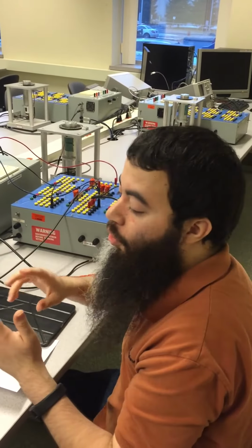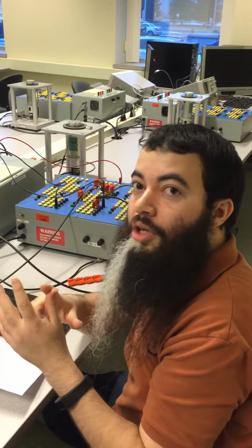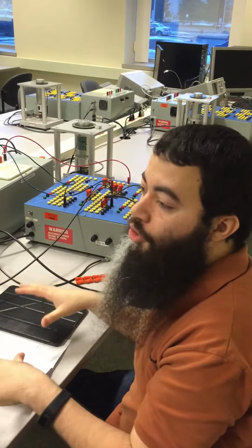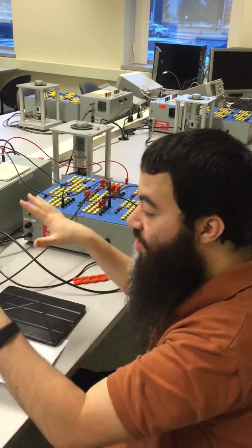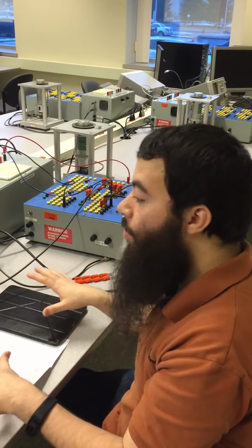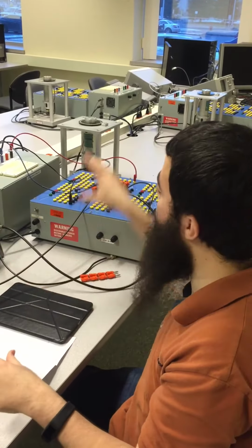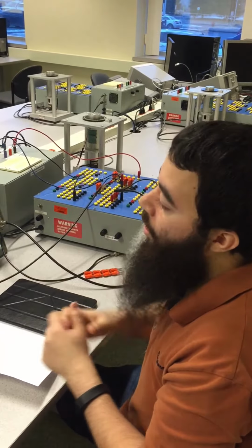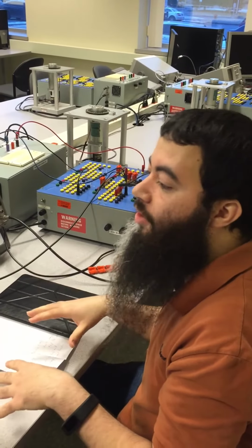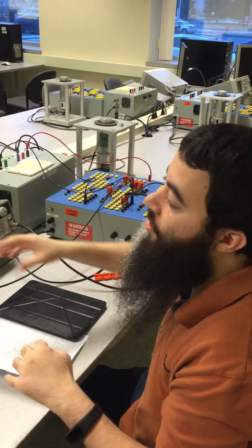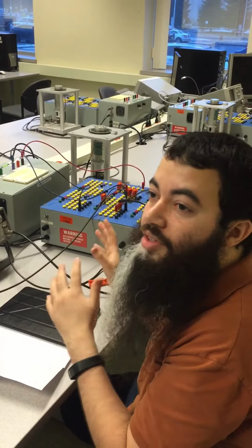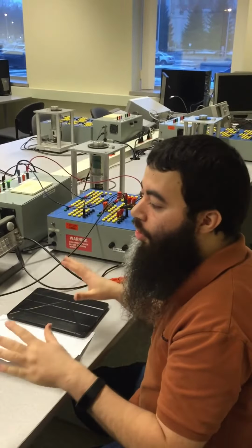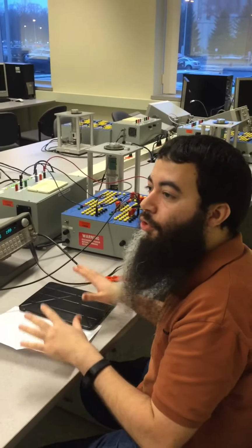only. So 2 points to be mentioned here. First of all, if you did lab 2 on this station, you should do lab 3, 4, 5 on the same station, because the values you get for A and tau m are specific only for this motor. They are characterized for this motor only. If you made your experiment for A and tau m here and you went anywhere else, there are differences between A and tau m for every single motor. So first of all, the station you work on for lab 2 is the same station for the rest of the labs.